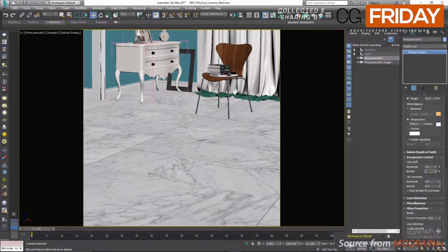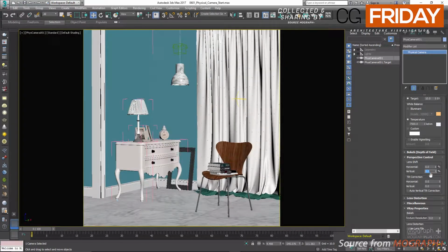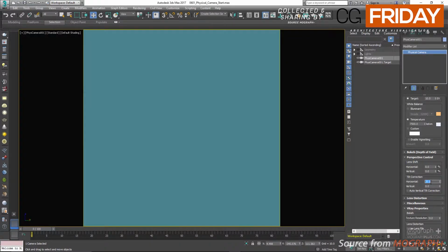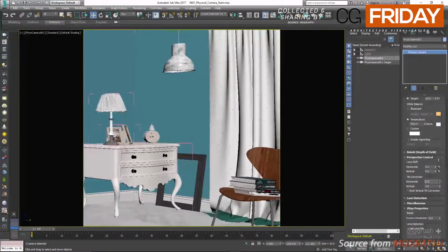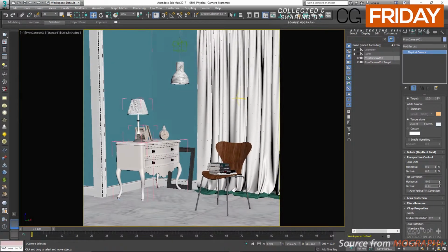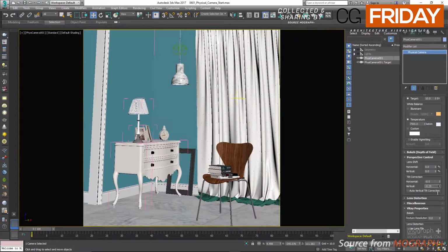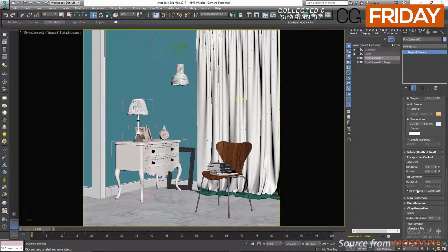In the tilt correction group, you can tilt the camera horizontally or vertically to correct the perspective, particularly in scenes where the camera is already tilting up or down, and to achieve the simulation of tilt lenses for 2-point perspectives. Also, auto vertical tilt correction: when this is enabled, the vertical value will be set automatically to align perspective along the z-axis, and it is very useful in exterior architectural visualizations to correct the perspective.